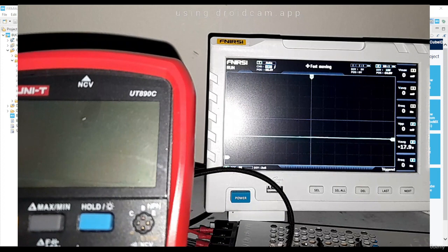And of course, I have to speak of the elephant in the room, which is the switching noise visible. Honestly, it's more of a thing with the source. I'm using an AC/DC converter. For better performance in the output, a linear power supply would have been fantastic to serve as the input, but I'm using an AC/DC, something that's very much available.